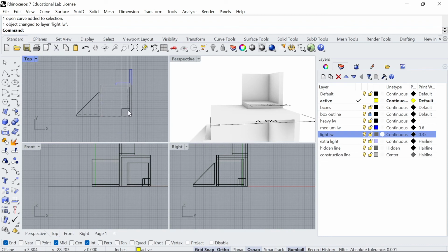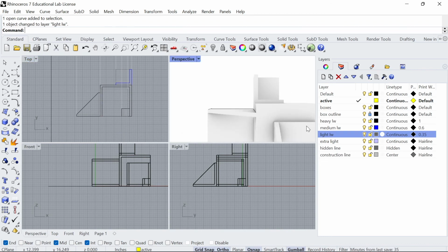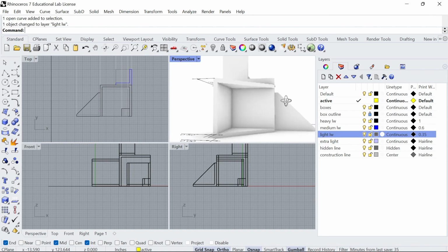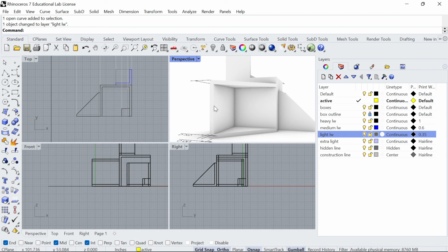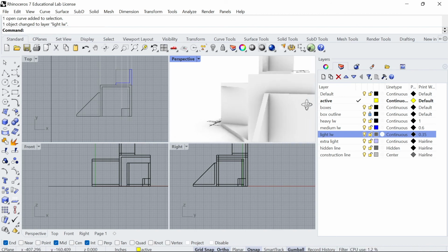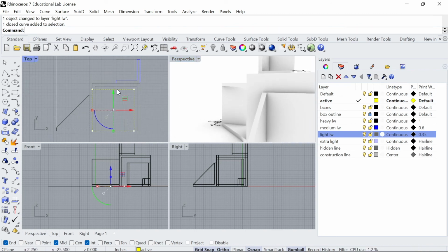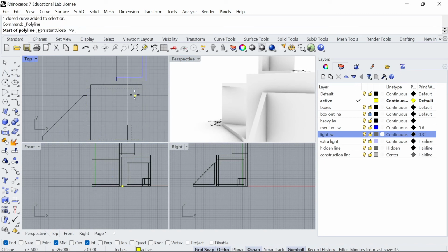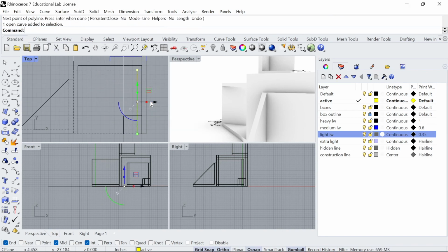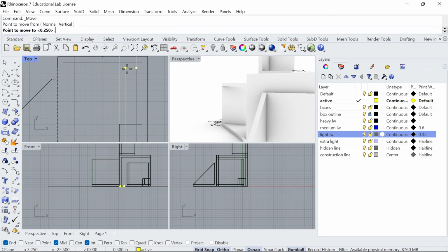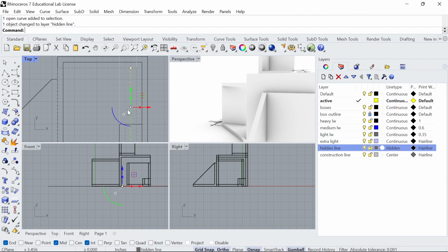All right, and then finally, you want to be aware of what's happening in the back right here. And for the most part, it's pretty simple. The only thing you want to consider is this thicker line. Otherwise, it's set as it is with this profile. So all I need to do is draw the line here just like this instead of exploding it because there's really no need to. Select this line and then move it 1/4 inch this way to the left, and then change that to hidden. Okay.